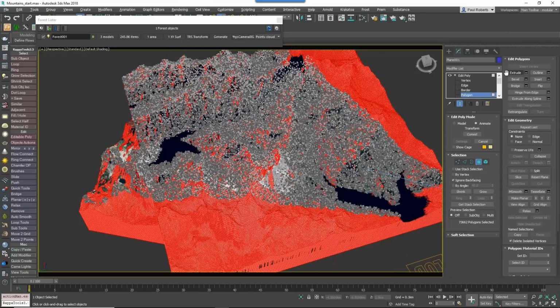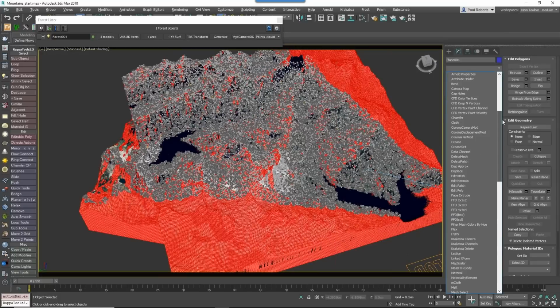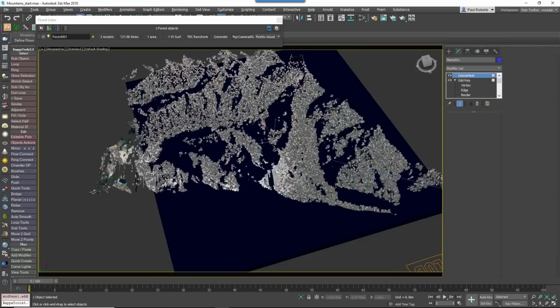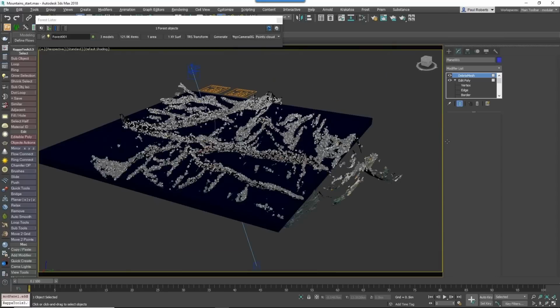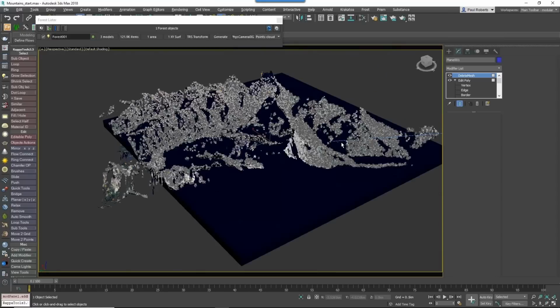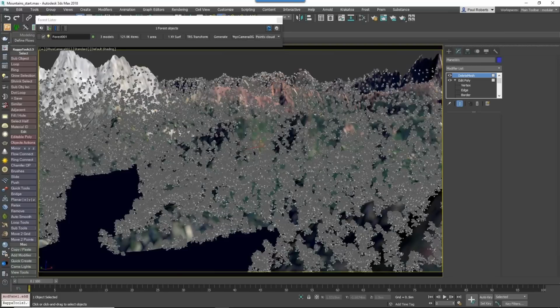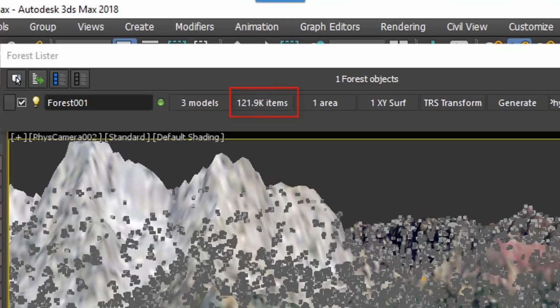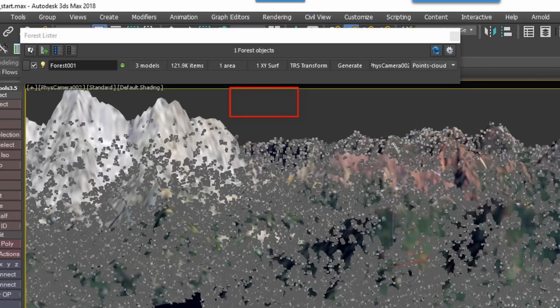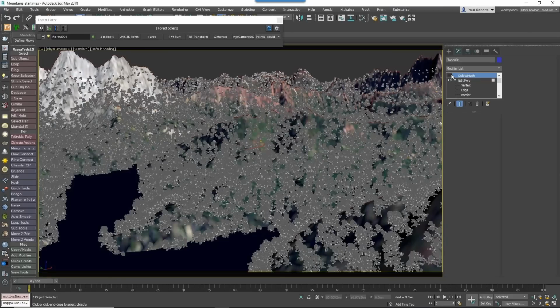Don't just delete them, because otherwise if you move the camera, you're in trouble. Pass them to a delete mesh modifier, and it will just delete all the polygons that the camera can't see. So from the camera's perspective, this scene is going to look exactly the same, but we've now got half the number of objects being scattered. So that's a nice tip for just optimizing scenes. And the good thing is, doing it this way with the modifier, you haven't done any permanent damage.